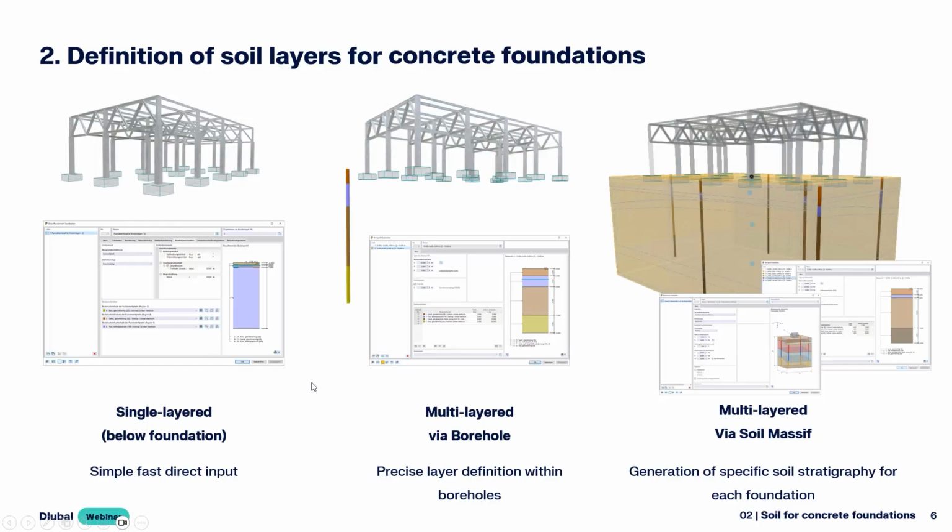If you have a layered soil below the foundation and you want to consider and define it, we provide the option to use the borehole dialog. For the add-on concrete foundation, the borehole dialog is provided too, so there's no geotechnical analysis add-on needed for using this solution. There you can go to the borehole as we showed for our advanced half-space method, define the soil layers and assign them to the foundations and use it.